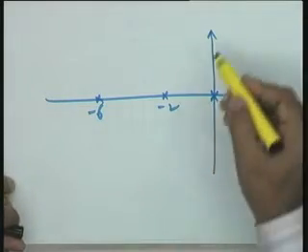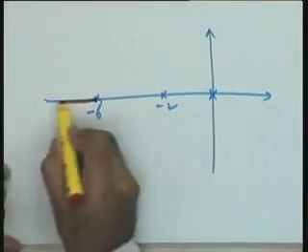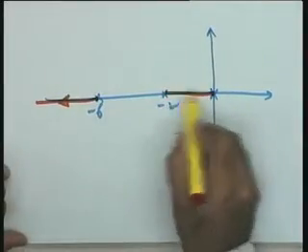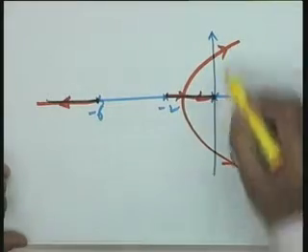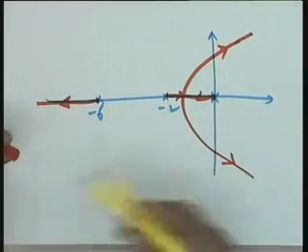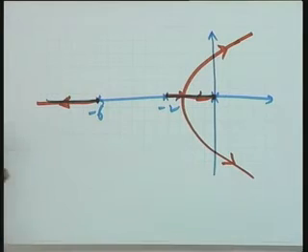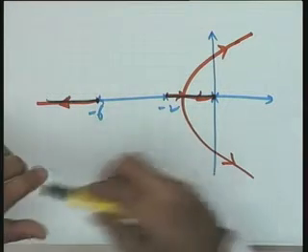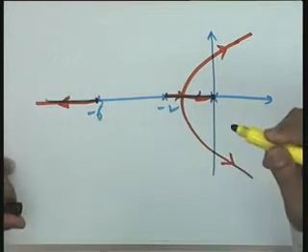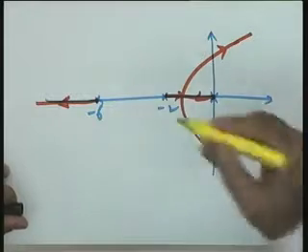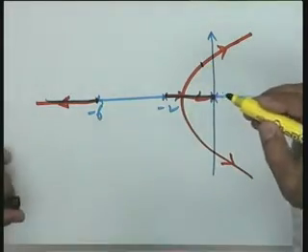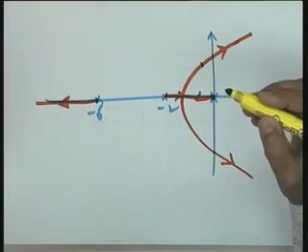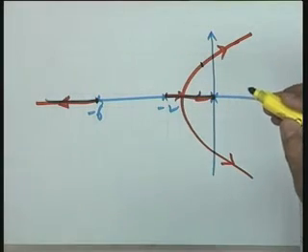In this particular case, the root locus is expected to be of this form: one branch going this way, two branches here, and these are the directions these two branches are going to take. This is your root locus. Now, you have decided K equal to 60 is the point which meets your steady state accuracy requirements. I would like the K equal to 60 point to be located on the root locus plot, so that I can evaluate the transient performance of the system.